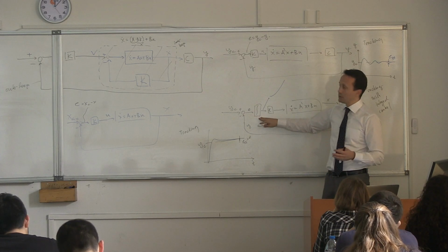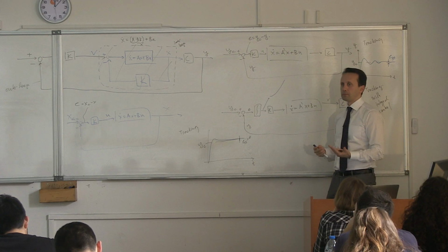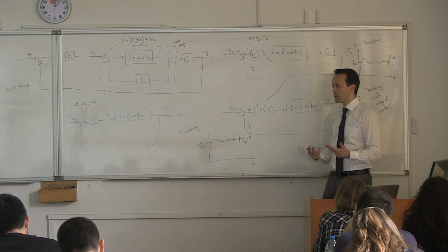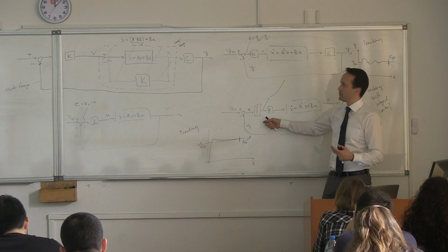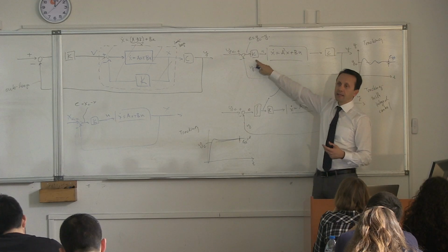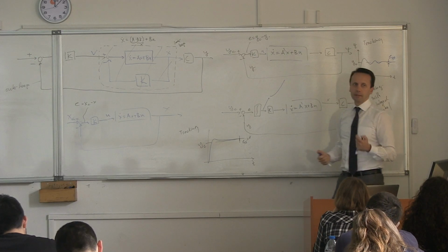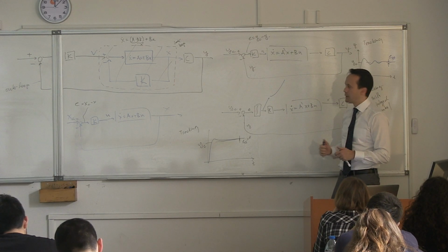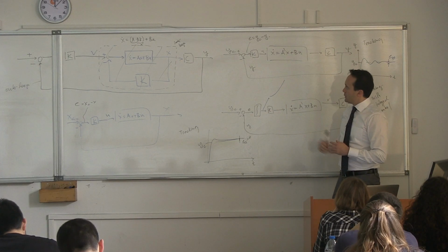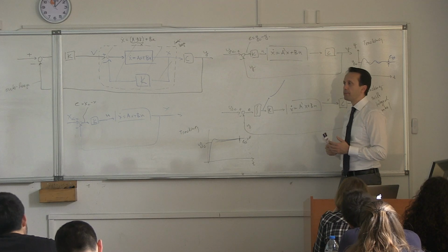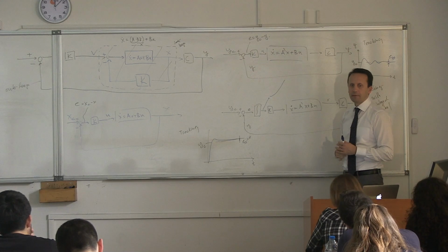So from a practical point of view, the integral is always kind of troublesome in real life when you start using it. That doesn't mean that we don't use integral, we use it all the time, but it's a little bit more troublesome. So a lot of people just add a k over here, and if you design this right and if it works, you wouldn't bother with an integral controller typically, all right? But you might use the integral controller as well. So this is kind of what I want to do. Do you understand all of this? Or do you have any questions?